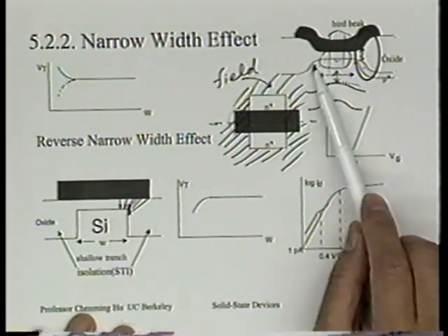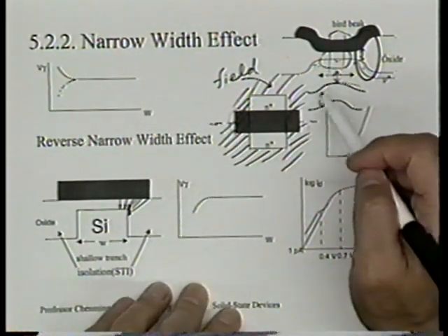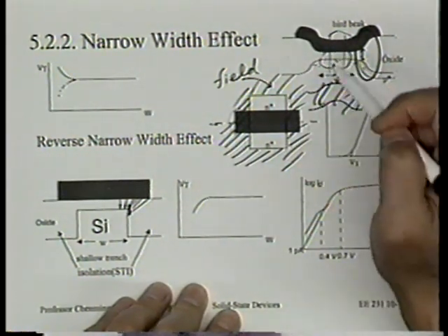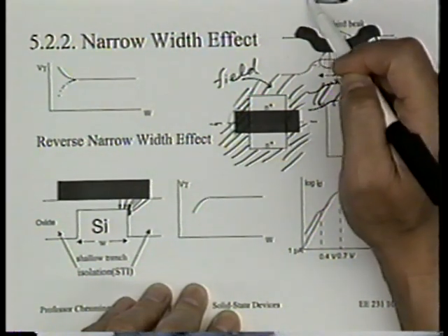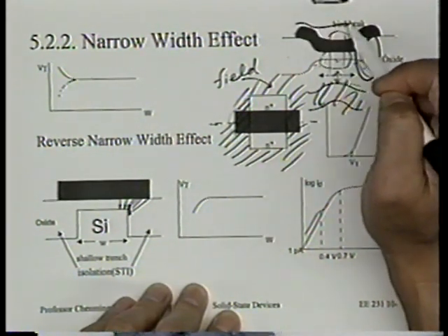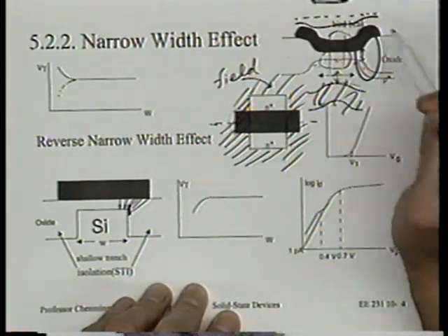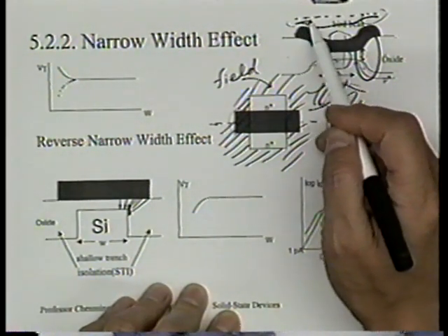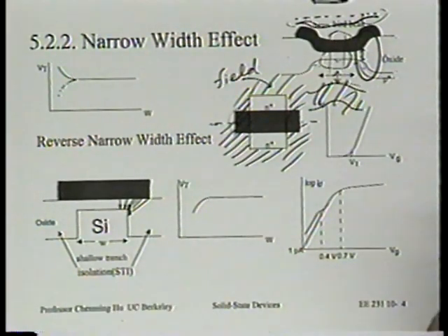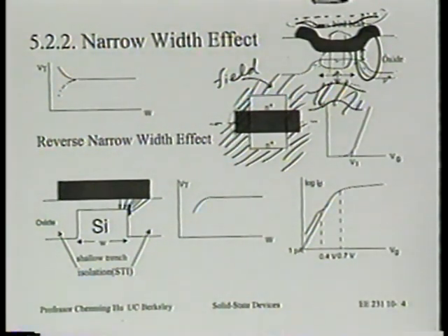All right? And depending on what this boundary condition is, closing or far off. I drew this band, right? This is probably confusing you. I'm sorry. What I have drawn really is more like this, the band picture. Did I do this right? Because this VT, if you want to visualize it, you probably want to visualize this way. It's more heavily doped P here, heavily doped P, more lightly doped P here. Is that correct? Yes? All right. So this is the case at the so-called flat band condition. Is that right?